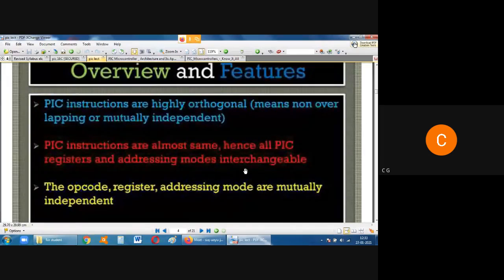But here, if you process data like multiplication, you set three registers A, B, C. C acts like a counter. You store the number to be added in register B, and you clear register A, and then you do add B always, and you decrement the counter. Now the content of register C you can directly store to the memory location. Okay, the content of register B you need not store because it is there, but the content of register A, you then store it.